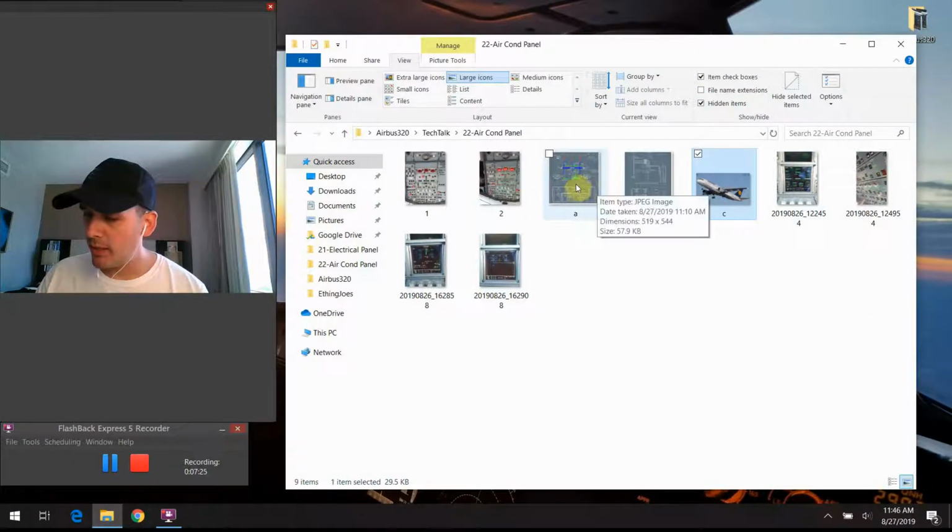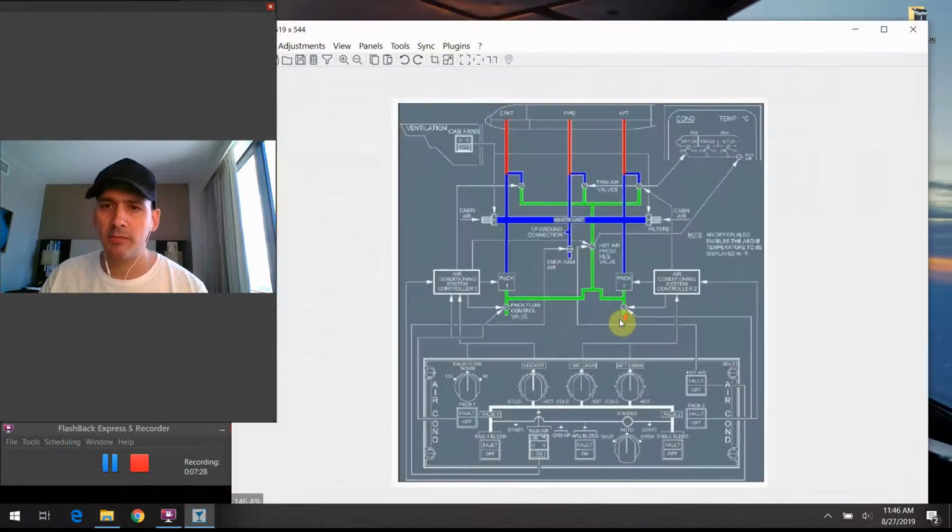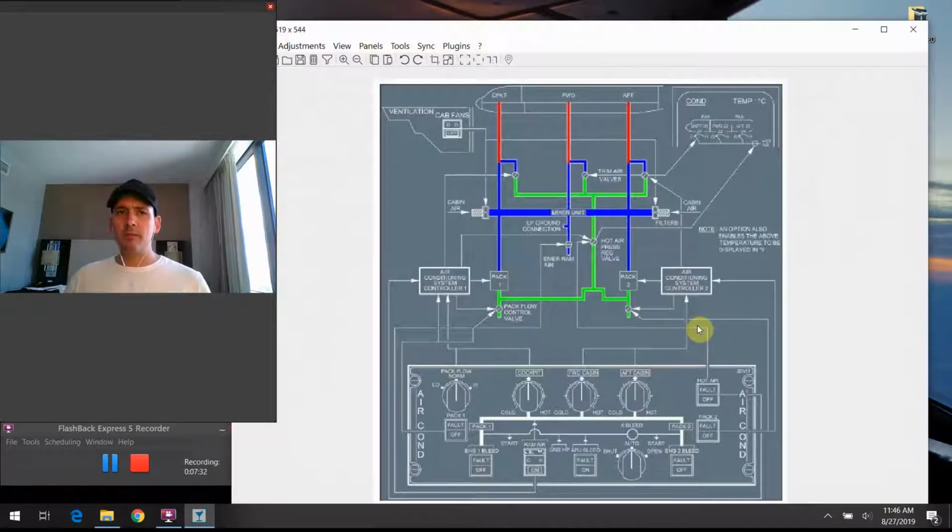Let's go ahead and bring this graphic up again and talk about just a few more things. Like we said, on the Airbus we have these different modes of cooling. We have something called basic, and we have this optimized cooling system. The optimized one is, of course, the normal way that we cool the airplane down. What this optimized business is all about is a way to fine tune everything going on inside the cabin. You can actually command different temperatures in different zones, because maybe one section of the airplane is a little bit hotter, maybe there are more people sitting back there as opposed to a forward section that has fewer people. So you're doing a little bit of fine tuning to keep everybody comfortable in their various areas of the aircraft, and that is regulated and controlled by these trim air valves here.